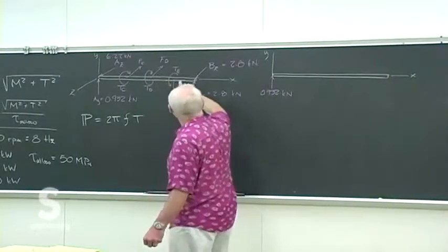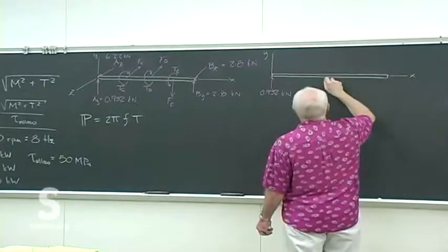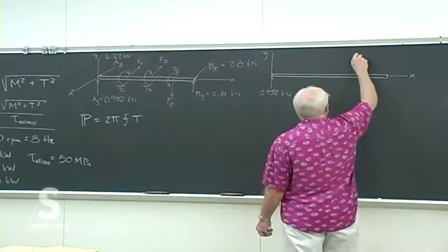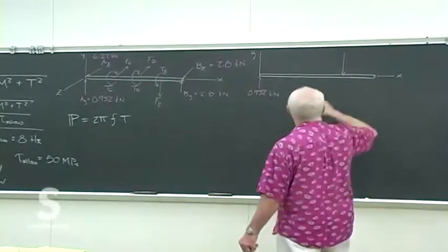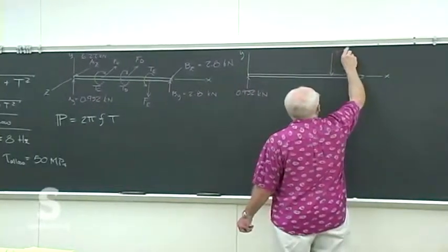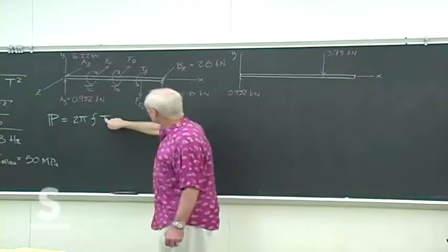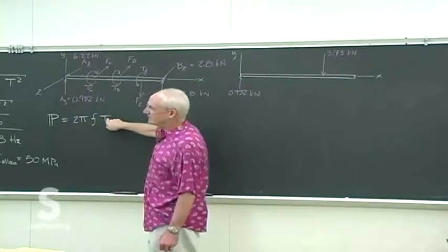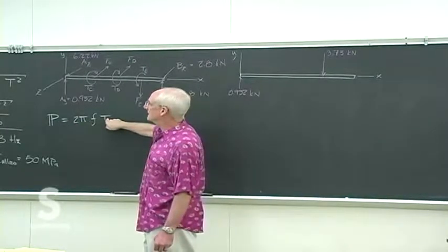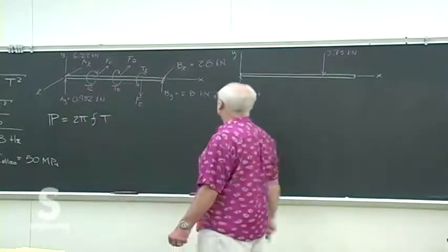Same with D, so we're only going to see the one at E, which will be something like that, and we know that to be the 3.73 kilonewtons. Remember, that's from finding the power coming in, the known frequency, figuring out what the torque is applied at E, then from that torque and the radius of the gear, finding out what the force is.